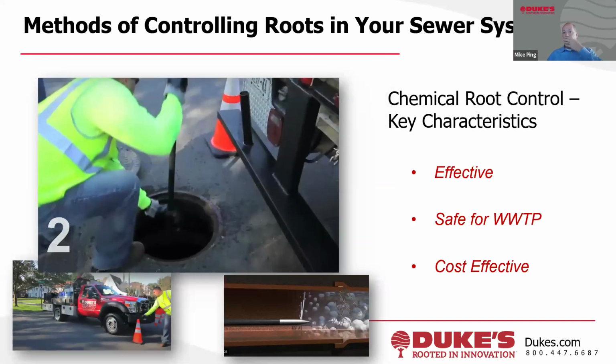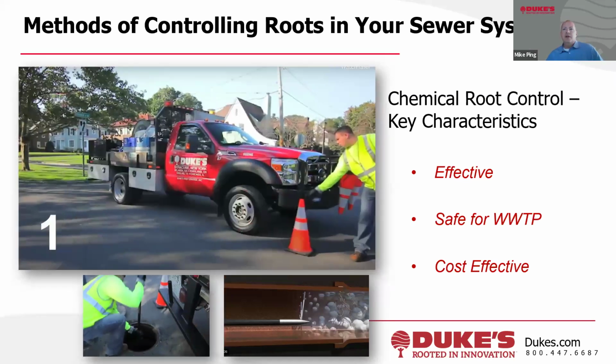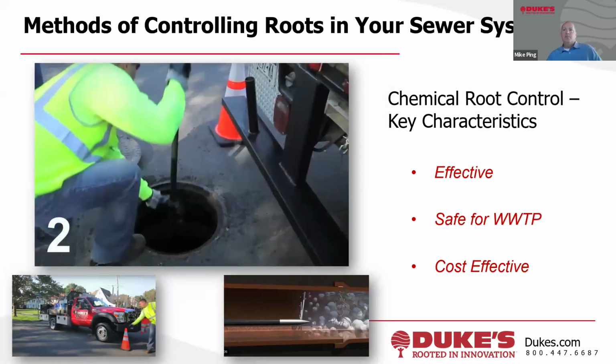So yeah, the first step here is the vehicle. You can see the specialty vehicle that's set up to apply the product. It pulls up to the manhole and does all the safety procedures. And the second step is the operator opens the manhole cover, deploys the, I keep wanting to call it the jetter system, but the applicator hose, and it gets pushed from one manhole all the way to the next manhole.